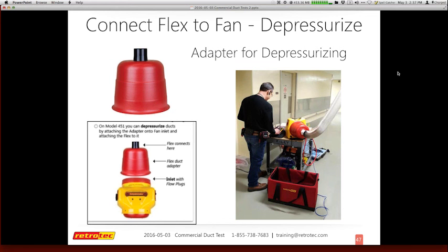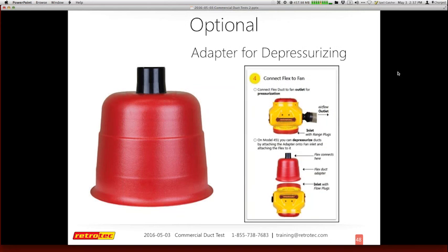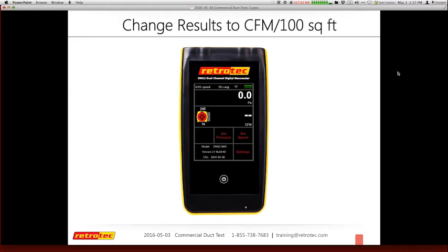So I can be running a test, and again, maybe I only got to 0.5 inches of water column, and I can get the gauge to extrapolate on the right. So here I can actually turn on the add feature and get my area leakage per 100 square feet live in the gauge. And again, I've handled all the other issues that may have come from either fan fluctuation or other pressure fluctuations, to give me a solid result right there in the gauge that I can use for my documentation.